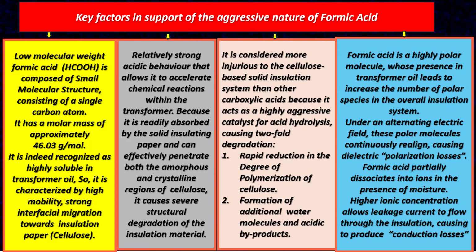Under an alternating electric field, these polar molecules continuously realign, causing dielectric polarization losses. Formic acid partially dissociates into ions in the presence of moisture. Higher ionic concentration allows leakage current to flow through the insulation, producing conduction losses.